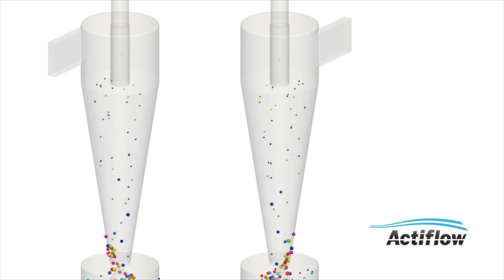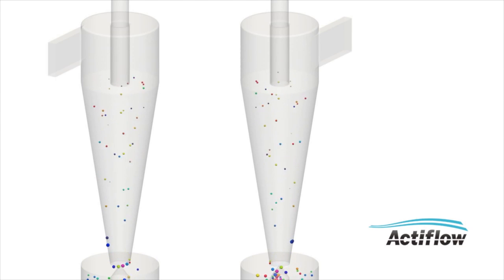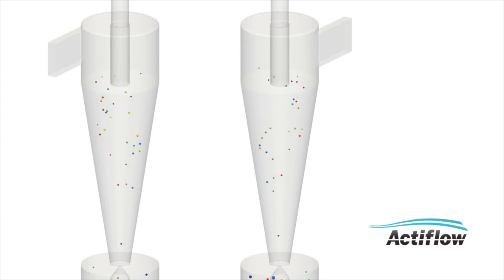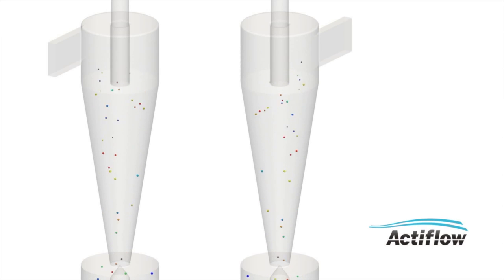Other important design factors are the diameters of the body, the inlet, and the outlet. The body needs to be longer with respect to the diameter. The inlet and outlet need to be small, but they vary with respect to the airflow. Higher airflow allows for larger inlet and outlets, and vice versa.